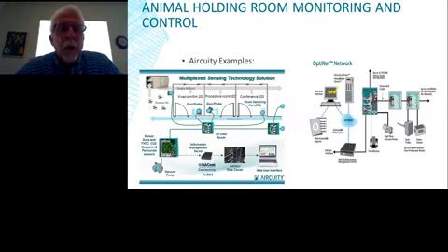What I've noticed a lot in a lot of the primate facilities that I've consulted or worked with is where they are actually able to look at particulate, and particulate is a big issue for us, and then monitoring or ramping up when there are high particulate times and decreasing airflows when there's decreased particulate times. This is essentially tied into washdowns and ability to monitor around those and be able to monitor the airflows around those and anticipate some of those ahead of time.